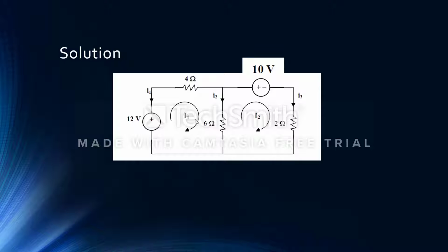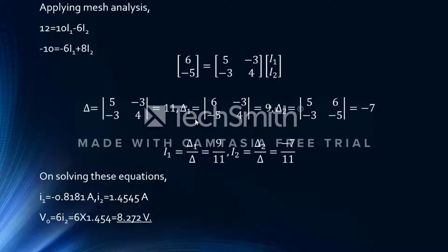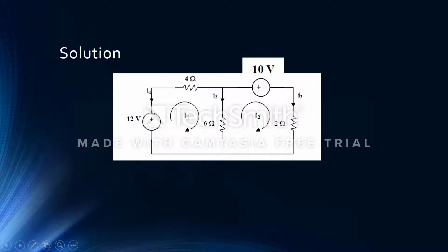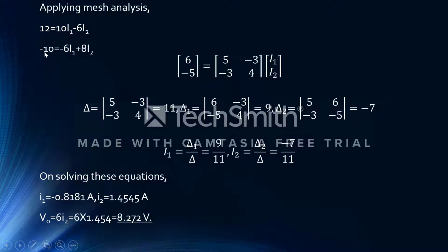Here for loop 1, using I1, we write the circuit equations. What we get is simply this equation: 12 = 10I1 - 6I2. Then on solving the second loop we get this. Now we are going to put down the same thing in a vectorial form.